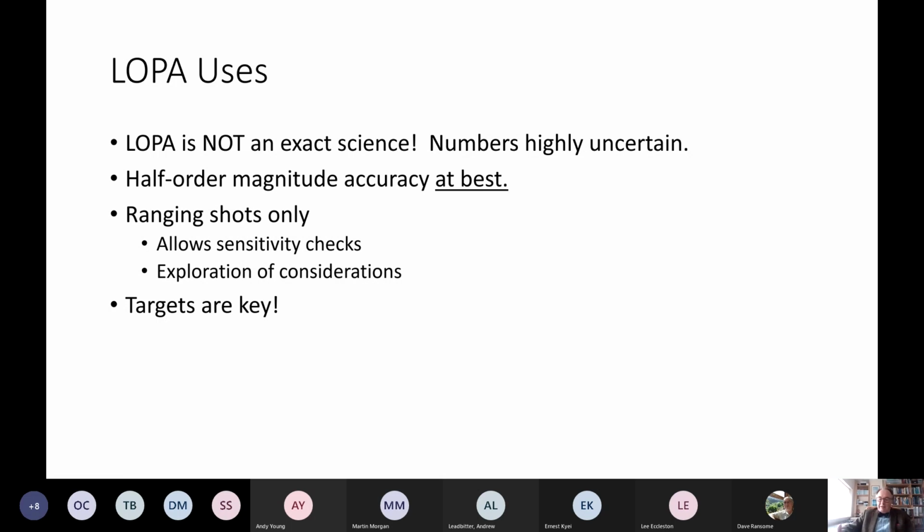If you make the targets that much more ambitious than is really warranted, of course, you will inflate the SIL targets for all your protection, and with that may come a world of grief and pain in terms of the engineering that in truth is not really warranted. That's the difficulty. I have known clients say, oh, we're going to do even better than that. We're going to go for 10 to the minus 7. We're 10 times better than everybody else. And it just brings a world of pain and grief. So not to be done on a whim.